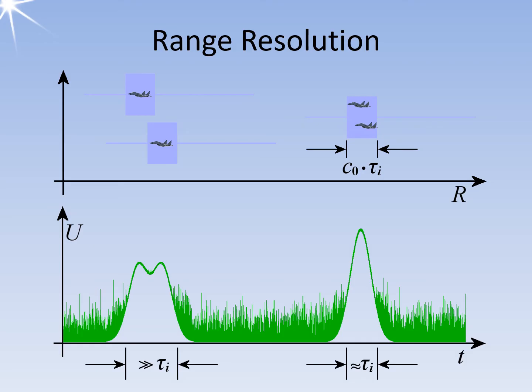Ideally, the transmit pulse is rectangular. However, due to the receiver bandwidth, it is less sharpened and resembles a Gaussian bell curve. Two of these closely spaced curves can be identified as two objects if the pulse maximum of the second pulse is located outside the zero of the first pulse. Then, a significant local minimum appears on the impulse roof, which proves that there must be two targets.